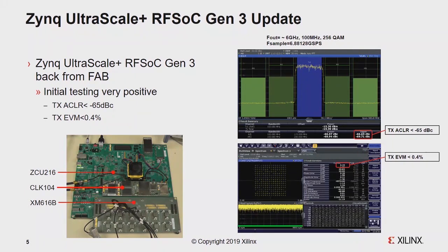Full scale output of the DAC is about 4 dBm, so it's pretty high output power, and that's of course the peak power, because that waveform probably has, I don't know exactly, around 10 or 12 dB peak to average power. And the typical system requirement in a wireless system is minus 45. So this performance is really quite good and doesn't limit overall system performance at all.